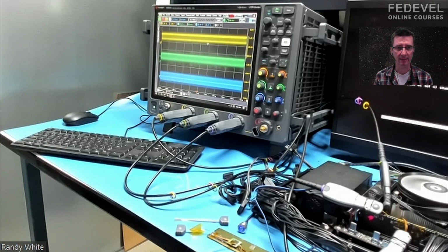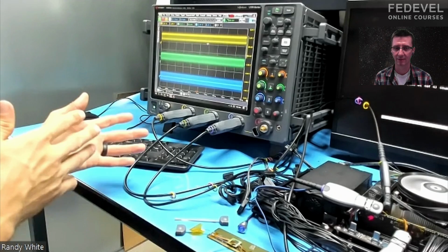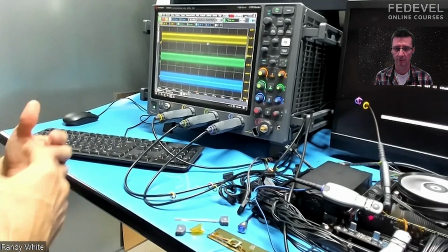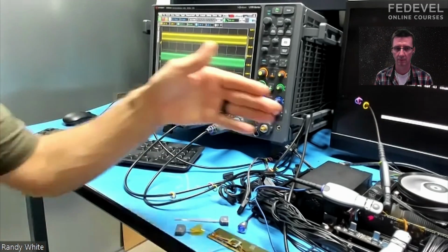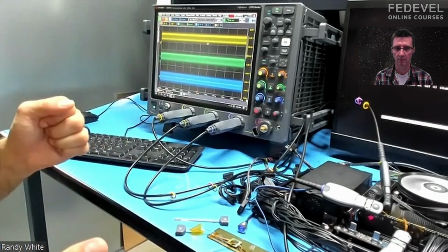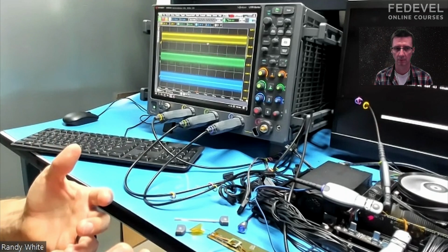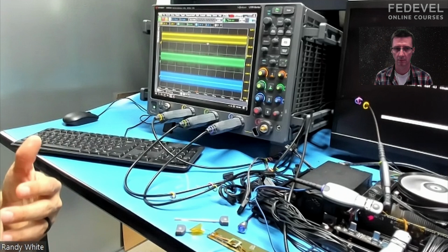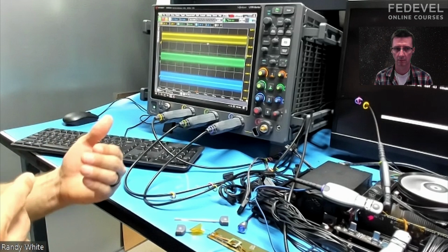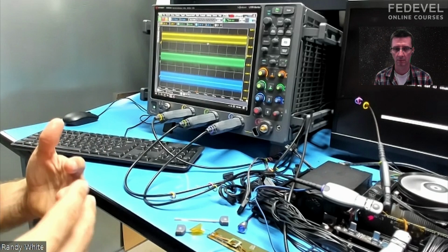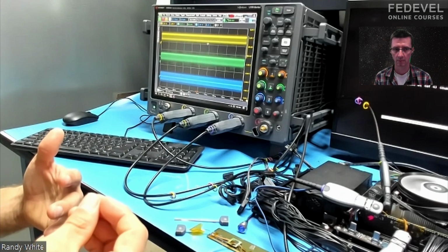Okay. But also, I believe the effect of the interposer and probe can be kind of eliminated if you use a really good oscilloscope. Yeah, well, that's true. A high bandwidth oscilloscope to preserve the signal so you're not filtering or loading it down. But equally important are these probes here that we showed connected to the system. The probe amplifier is meant to present a high impedance to the system. And when I say high impedance, at DC, it's 25K or 50K ohm. That's such a high impedance. It's not pulling off a lot of current from the system.